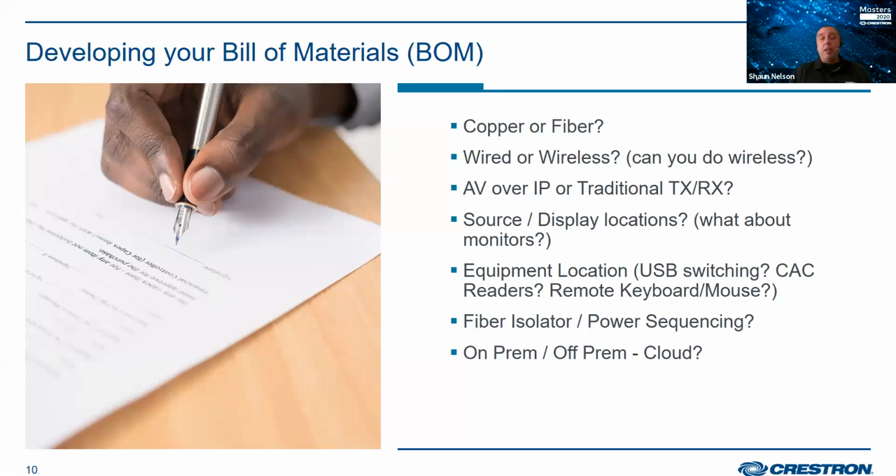The real benefit to NVX is the fact that that SFP port allows for different types of fiber. So you're no longer locked into a single mode as one transmitter or a multi-mode as one transmitter. You're not separate product lines now. It's just a matter of switching out the actual SFP itself to be able to support multi-mode or single mode.